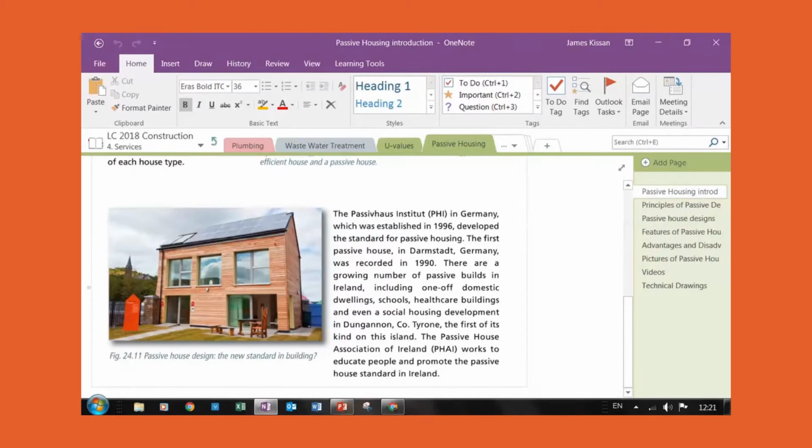Now, this here is what a passive house looks like. Looking at this, a couple of things from the photograph that people should be aware of: the windows downstairs are actually full length windows and doors, so as to get in as much solar gain as possible. Also upstairs, very large windows. Your traditional house has a lot smaller windows, because people don't want to put in a lot of windows, since a lot of heat is lost out through windows. So in a passive house, we have large windows, but they have to be really high efficiency.